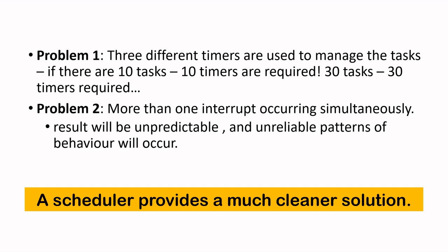Now, for example, if we have 10 tasks, we would require 10 timers. If you have 30 tasks, then we would need 30 timers. That can be a problem because most microcontrollers do not have that many timers. So that's problem number 1.